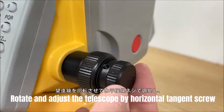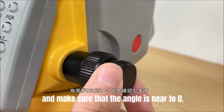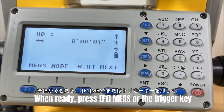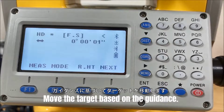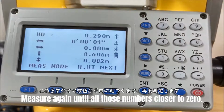Rotate and adjust the telescope by the horizontal tangent screw and make sure that the angle is near 0. When ready, press F1 measure or the trigger key to measure the current target. Move the target based on the guidance. Measure again until all those numbers are closer to 0.